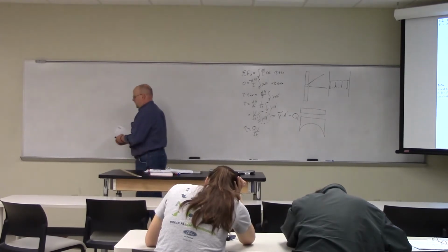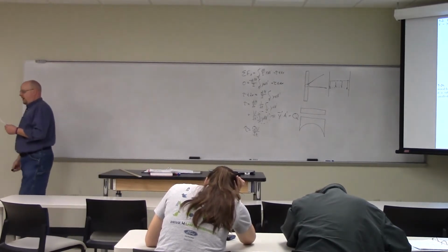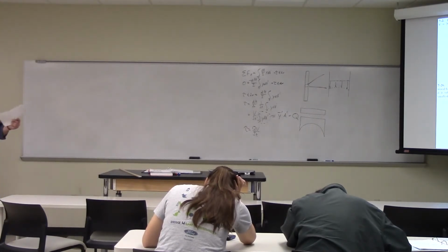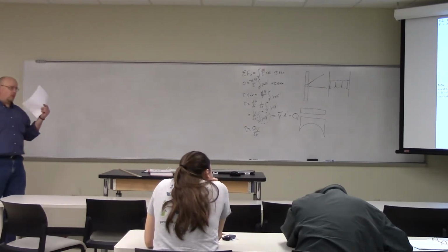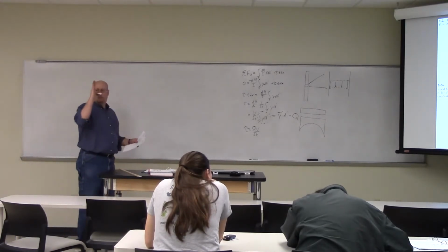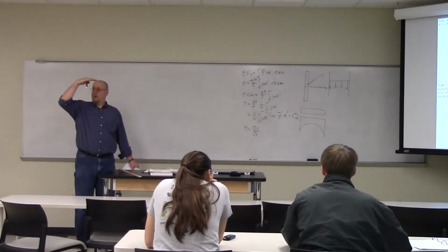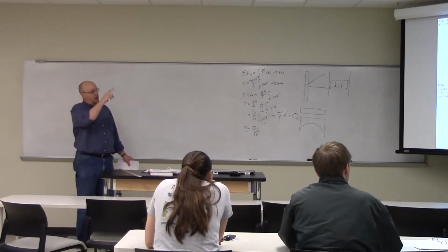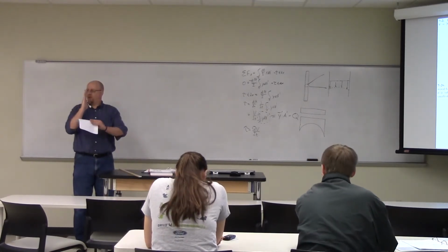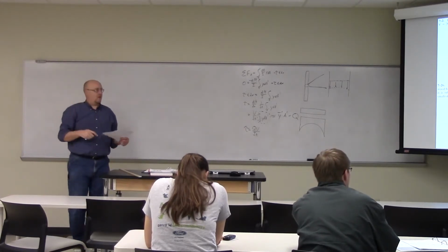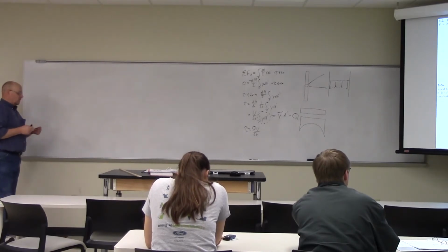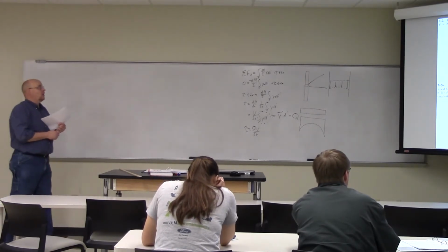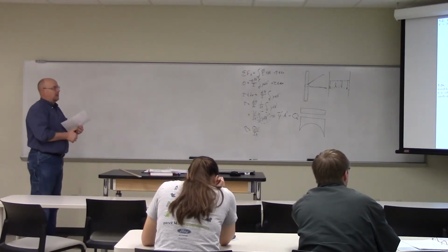Okay. If the wide flange beam... The flange is the top, the web is the middle. I was trying to come up with those words sometime last week or the week before, and I couldn't remember web and flange. The vertical piece is the web, like a spider web, of the I-beam, and then the two cross pieces are the flanges. So we have a wide flange beam. Flanges are wide. Subjected to a shear of 20 kilonewtons, determine the maximum shear stress in the beam.